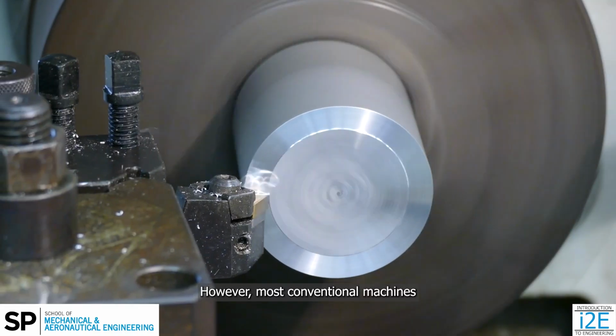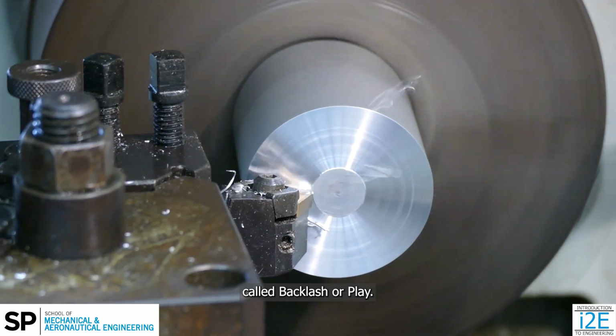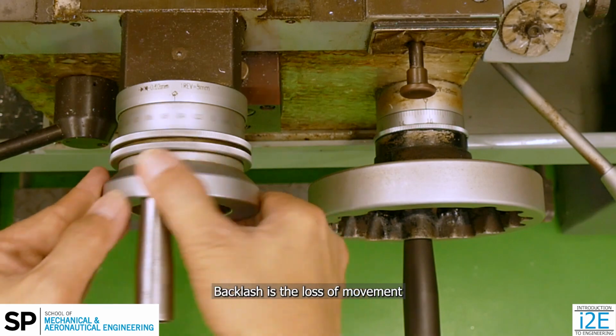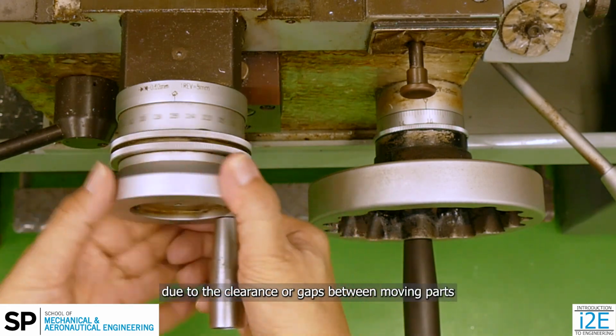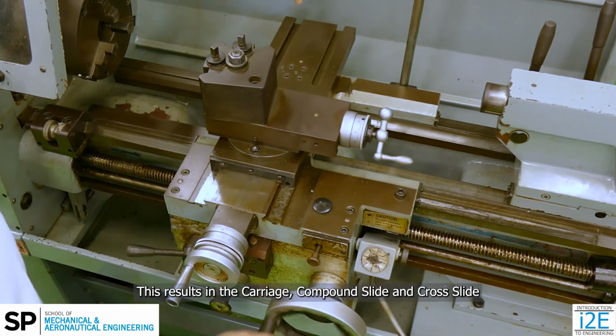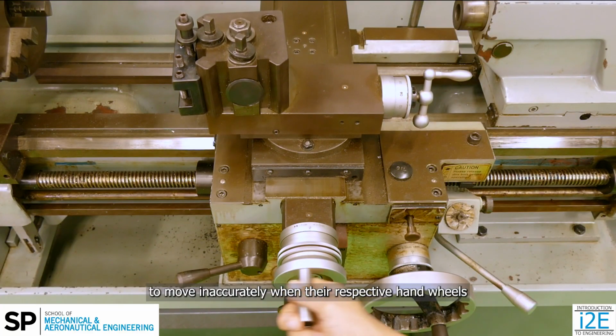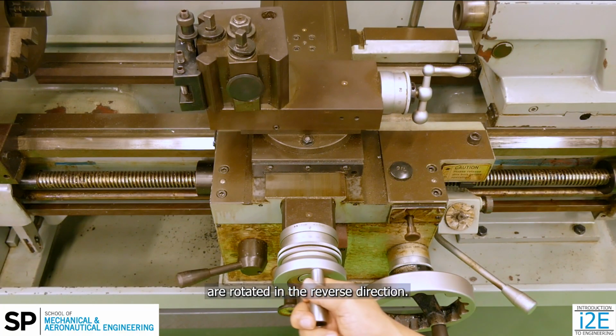However, most conventional machines have an inherent mechanical problem called backlash or play. Backlash is the loss of movement due to the clearance or gaps between moving parts, such as a lead screw and a nut. This results in the carriage, compound slide and cross slide moving inaccurately when their respective handwheels are rotated in the reverse direction.